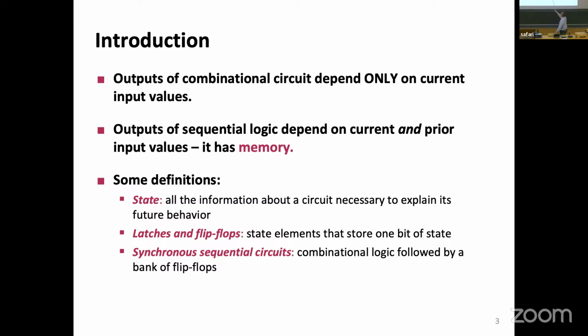Awesome. So, as you said, outputs of combinational circuits depend only on current input values, which is technically very good. It makes them very reliable. It's easy to visualize them. You write a truth table, provide a couple of inputs, you have a couple of Boolean equations, you know what the outputs are. Easy, nice, and predictable. Also, sort of kind of boring, because all you end up doing is writing them in equations of sums of products, products of sums, something.